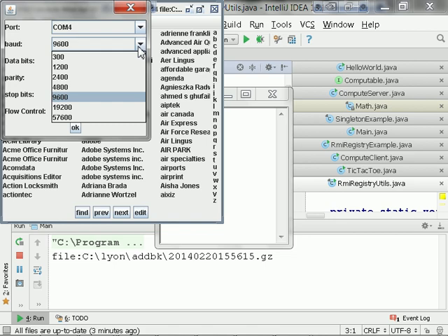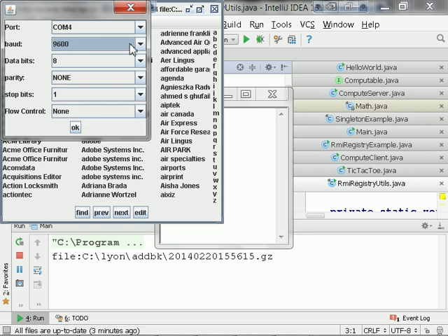You say 10. And I say, aha, so you're transmitting at 100 bits per second. So that's your symbol rate. So then comes the number of data bits. Data bits are going to be grouped together in characters. And those characters can have 8 or 7 bits. In this case, actually 5 bits. I've never seen anyone use that, though.